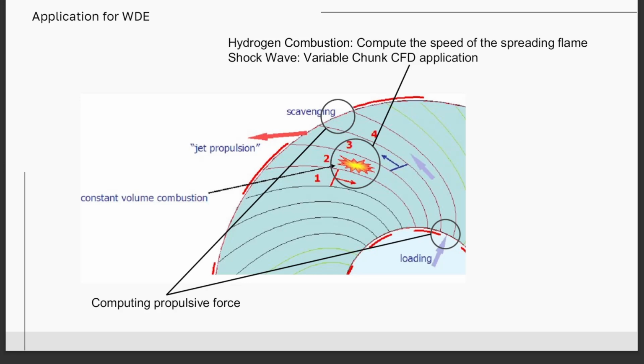In the shock wave generated in the wave disk engine channel, the shape of the chunk can be designed as a spherical shell with micro-thickness or using the cross-sectional area of the channel. If the chunk shape is chosen as a spherical shell, the position of the computational particle is fixed at the exact points where the combustion occurred, meaning individual particle motion alone cannot account for wave reflection.